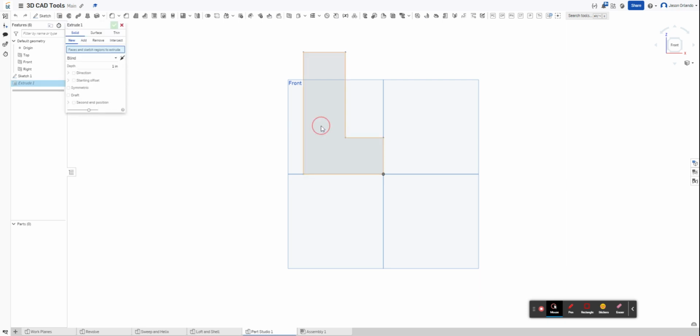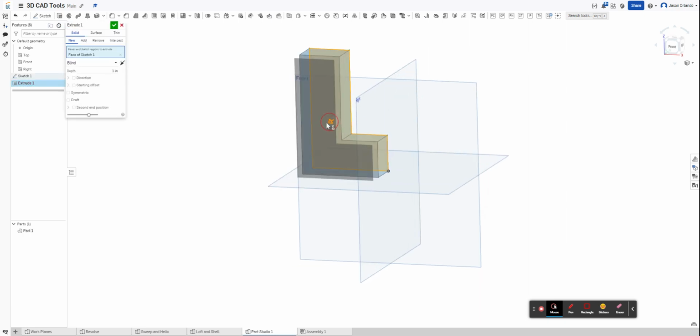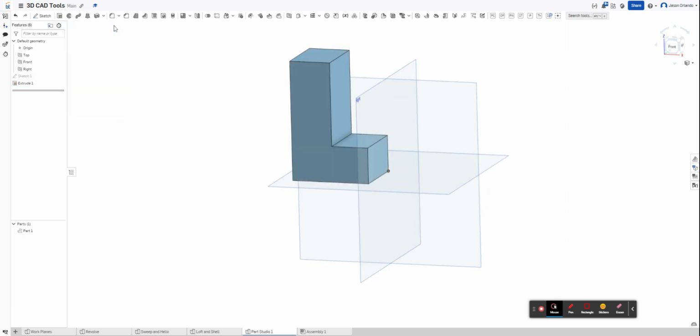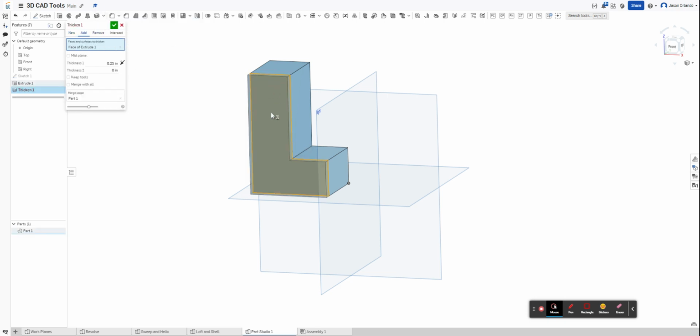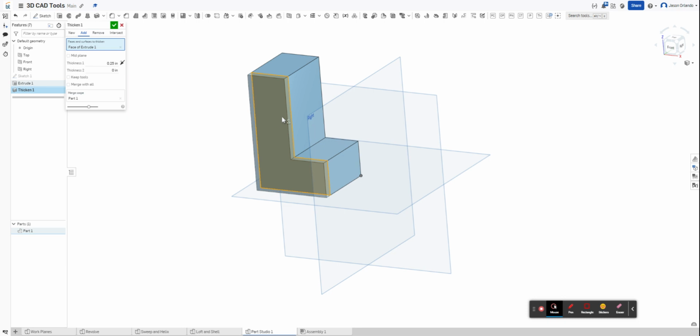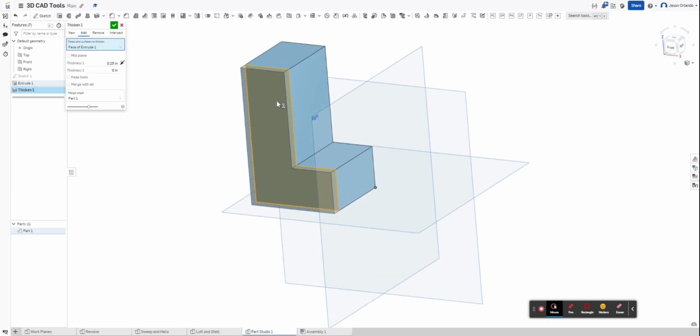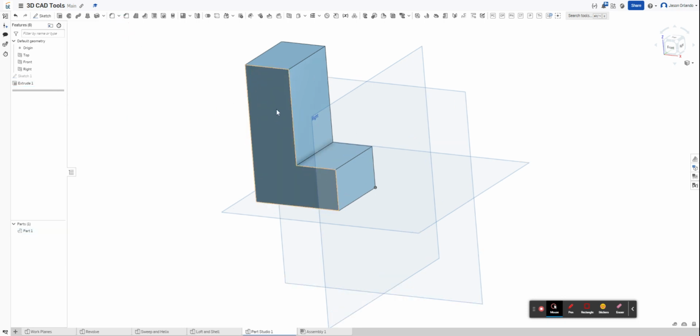And I'm going to extrude that because I want just a solid object with some edges to choose. So with this, I wanted to show you some other tools here. Kind of wanted to skip over that one, but I guess thicken up, we can cover real quick. Thicken, you can choose a face, and you could extrude too, but it adds to that face and thickens the part. I'm not going to actually thicken that, but that's a part right there. You could investigate those a little bit yourself.